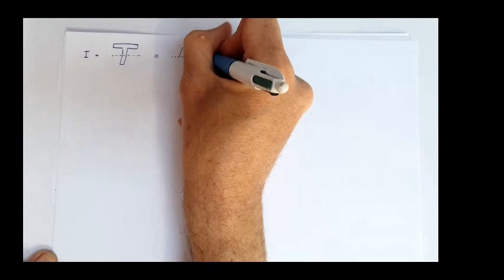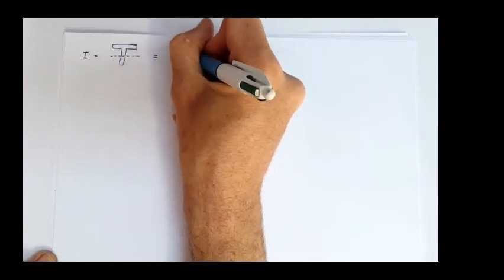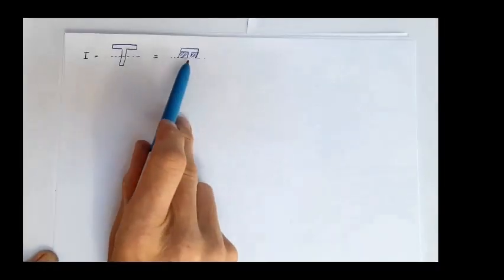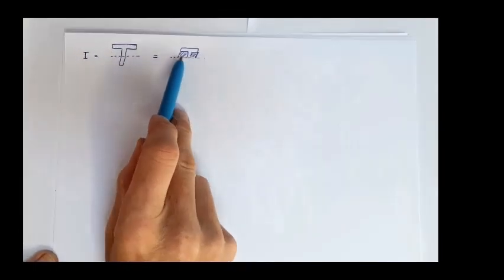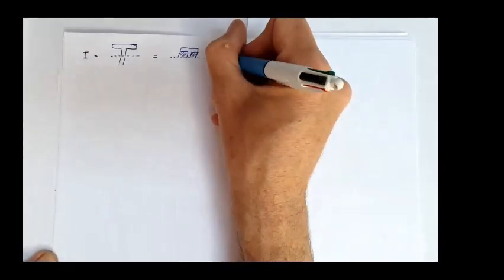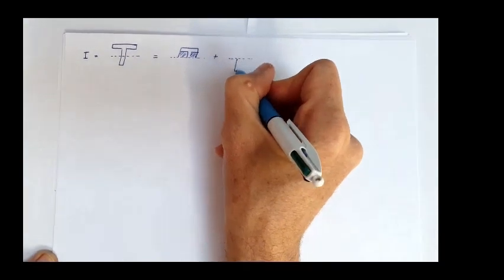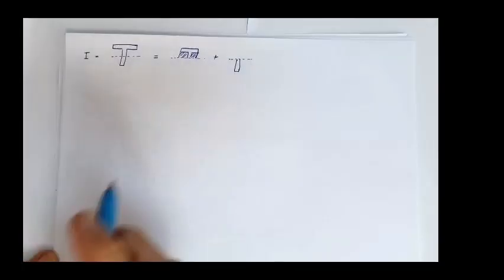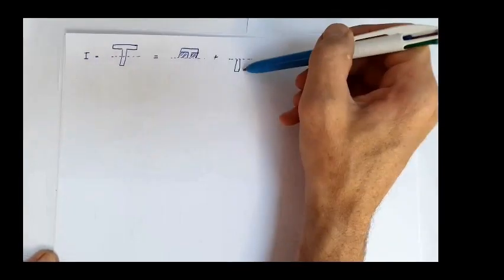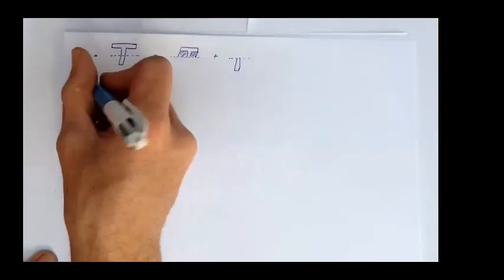Let's calculate the second moment of area of that rectangle and then subtract that rectangle and that rectangle. So my overall shape minus this shaded region minus this shaded region. And then I'm going to add on, to that same axis, a bit on the bottom this time, and add on this part here. We know this distance now is 109.4 millimeters, which we've just calculated.